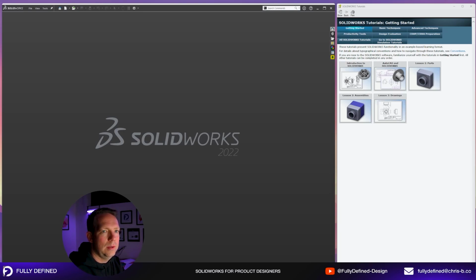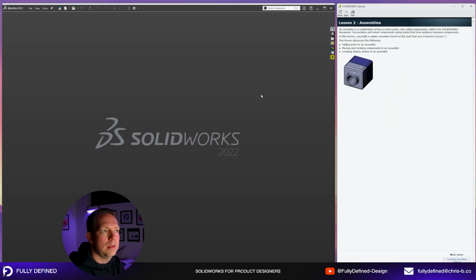Tutorial 2 that we're doing on our top 10 list for product designers is Lesson 2, Assemblies. An assembly is a combination of two or more parts, also called components, within one SolidWorks document. You position and orient components using mates that form relations between components. In this lesson, you build a simple assembly based on the part you created in Lesson 1.